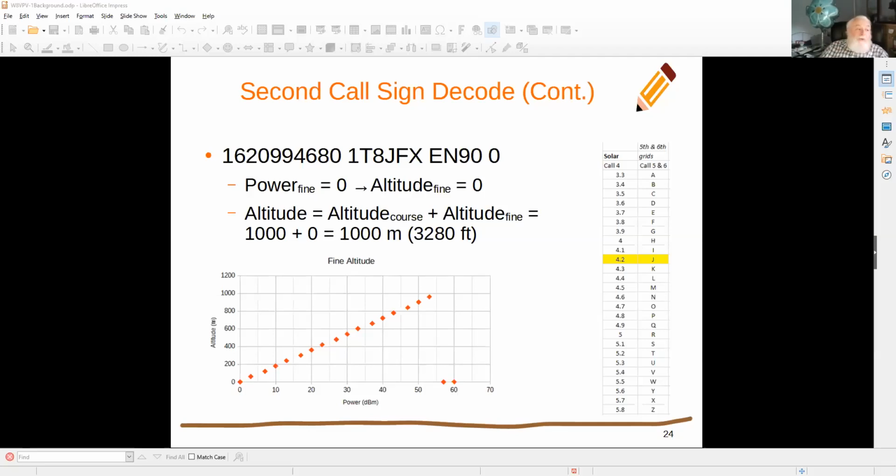The actual transmitter for the WSPR balloon here is really just a programmable oscillator. Because the bit rate is so low, all you need to do is change the frequency by a single hertz to encode the data here, or by a few hertz. I forget how many different tones are in there.